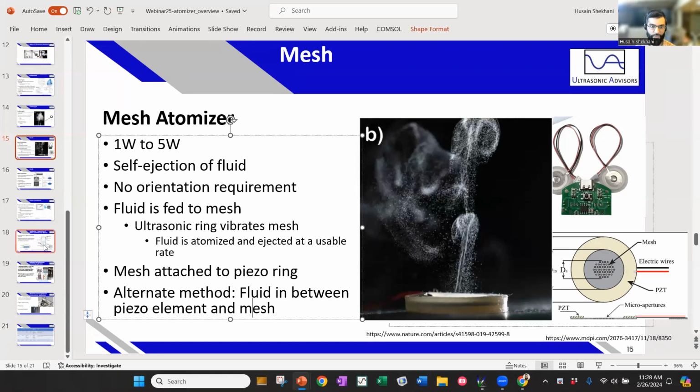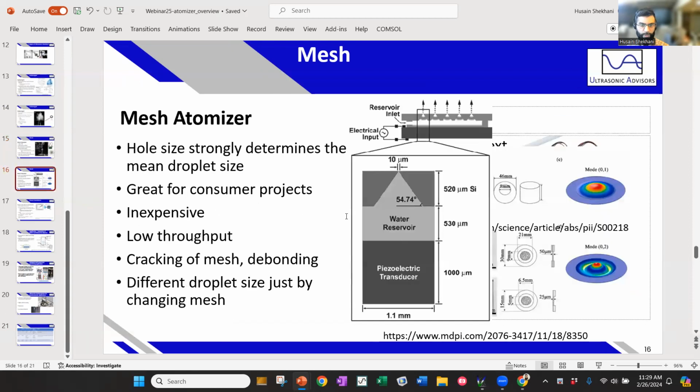So then it's similar to a submerged transducer where you're driving energy toward the surface, or toward the air-fluid domain, but you're not really driving it toward that area. You're driving it toward the mesh, so you're pushing the fluid out of the mesh. That actually makes the piezo construction more reliable, because a common failure point is cracking of the mesh element, debonding. So it does improve your reliability, but you're not as mechanically efficient because you're not directly applying energy to the mesh anymore.